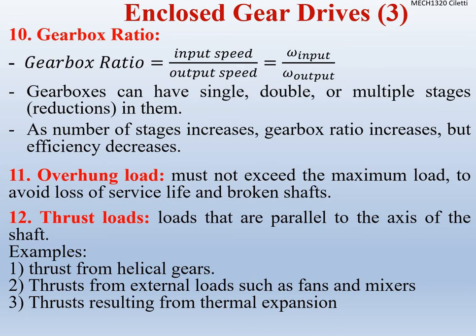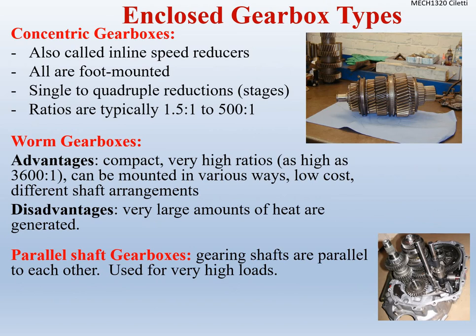So where do we get thrust loads? Remember, those are from helical gears. External loads, fans, mixers, things like that. You've got centrifugal force on fans, and those sorts of things. Thrusts result from thermal expansion as well.